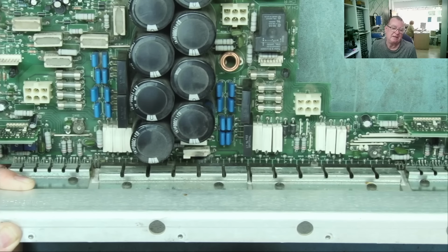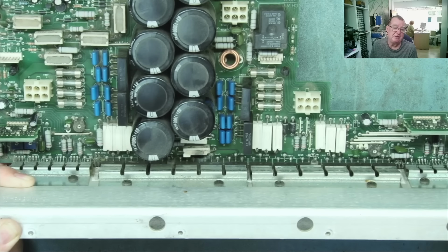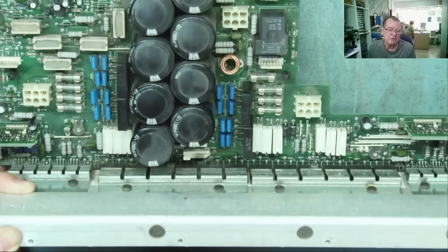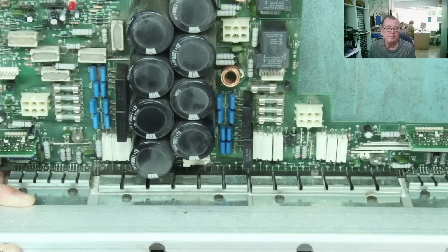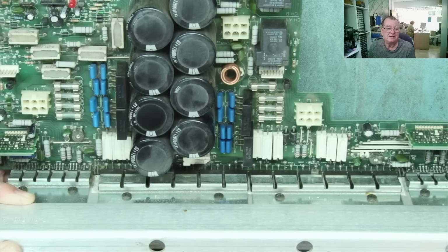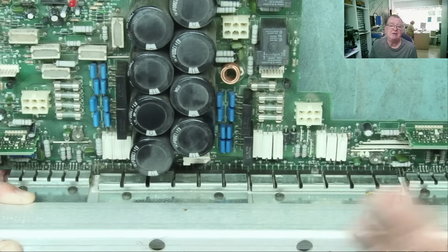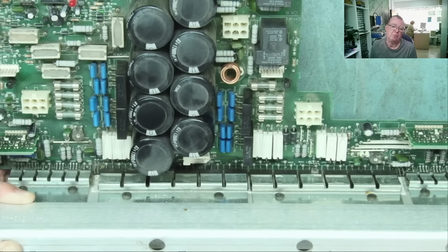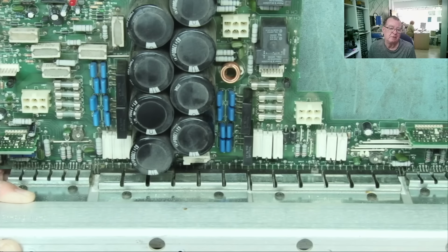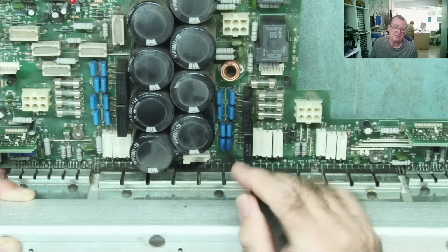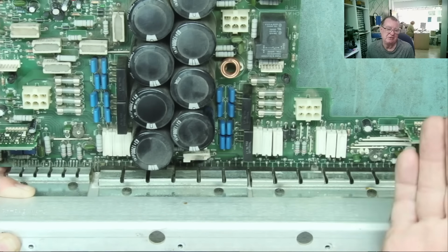Specifically, you'll find that in cases where the amplifier is integrated into a speaker, an active speaker. The same with a heater element. If your PCB has come from a coffee maker and one of the triacs is short circuit or open or blown up, you need to find out what that is driving and then go and check the heater element or the wiring in the coffee maker. Is there a short circuit somewhere? Has something overheated? Has something failed and then caused your component to explode or just go short? And the same, what is driving your faulty component? Is that okay, or can I just easily change it?